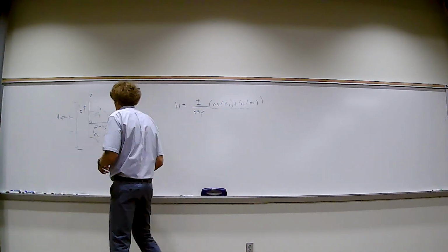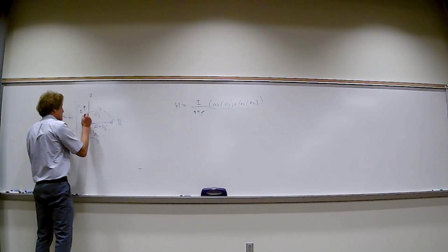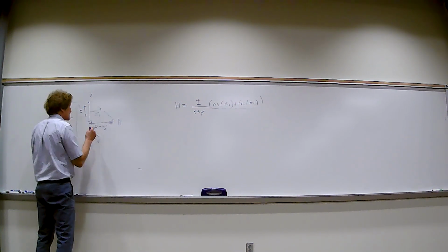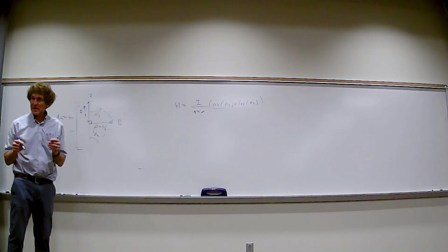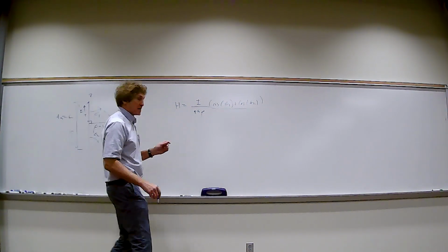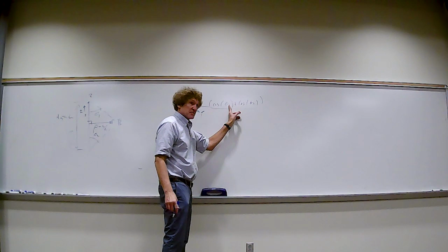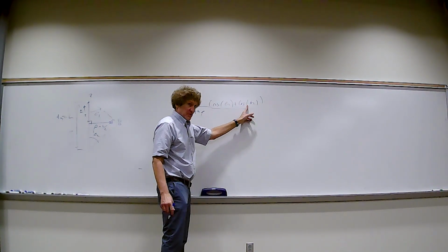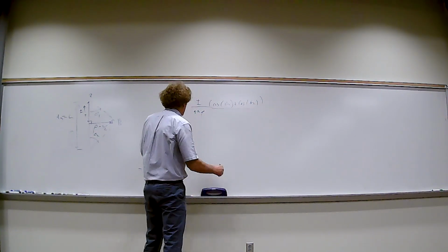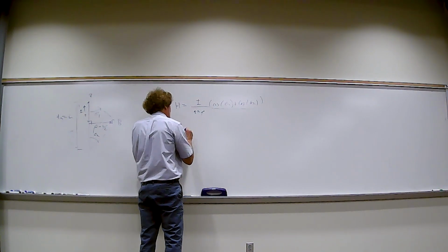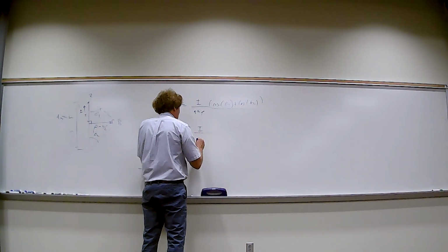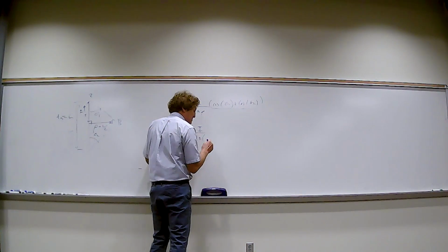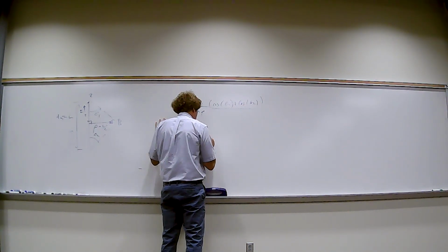All right, so y'all agree that this would be 2 from here to here. This is out 2, so this is 45 degrees. Does everybody agree with that, class? So if you do the math on this, we're going to get cosine of 45 degrees, which is 1 over square root of 2. Cosine of 45 degrees is 1 over square root of 2, correct? Right? So now you're going to get this. The H field at the center would be I, that we calculated, over 4 pi, and this is 2 centimeters would be a rho, or 2 times 10 to the minus 2 here.